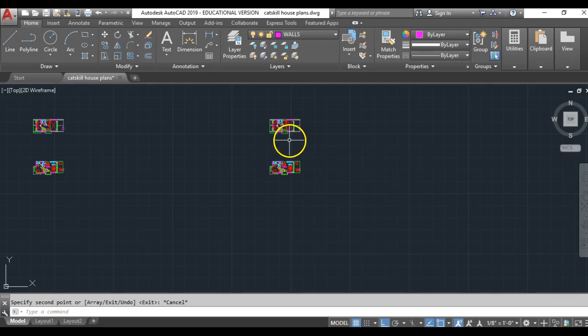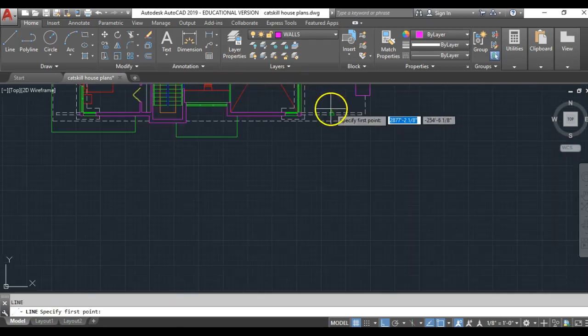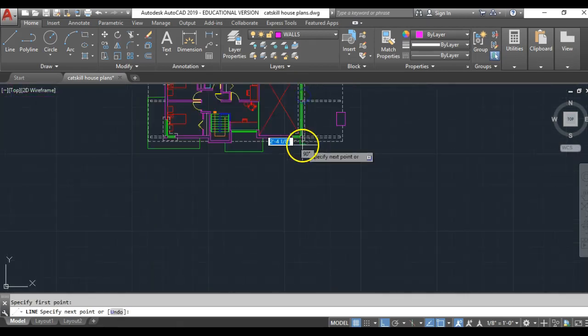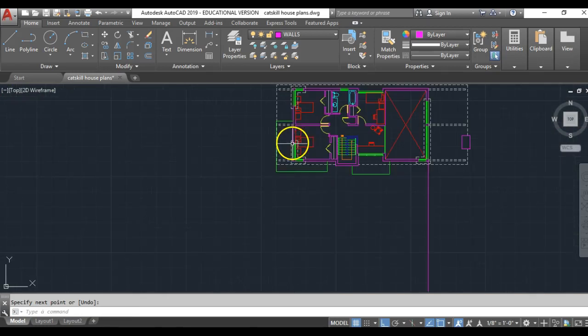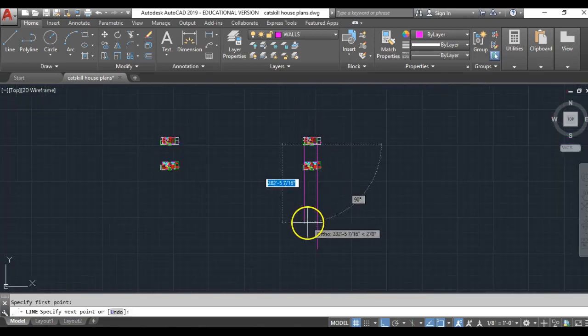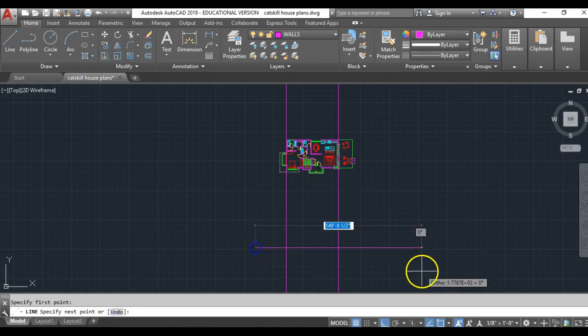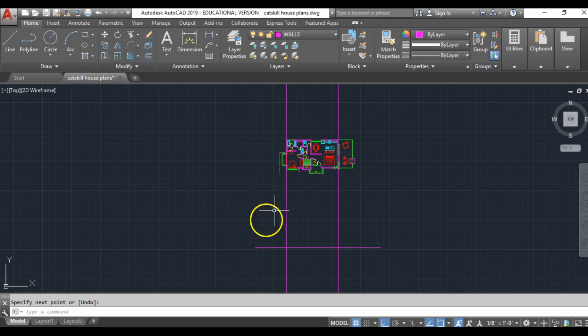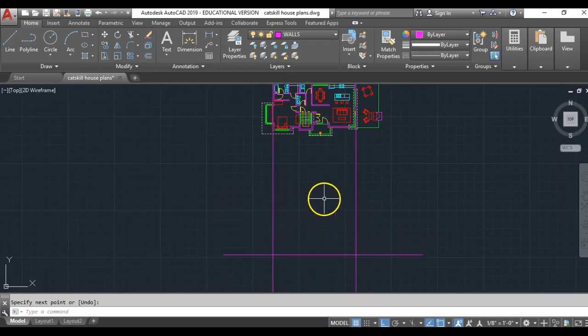Okay, so what I'm going to do is start drawing down. I'm going to pretend to draw an elevation, if you will. By that means I can draw from my exterior wall down. I can just snap to a corner and draw down. I could start from this corner and draw down. And I can draw a ground line across. I should mention, you're going to want to use layers. I have my layers on wall. I intend to make a follow-up video that talks about layers for elevations. But you definitely want to watch that before you get very far drawing your elevations, so you can draw in the correct layers. Of course, you can change layers at any time. But anyway, here's a ground plane, and then you might come up.